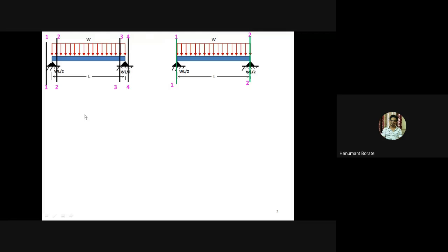Now SF at section 1-1. Now follow the sign convention rule. Sign convention: if we take a section and consider the left part of the section, then treat upward forces as positive and downward forces as negative. Okay. Now SF calculation, SF at section 1-1, or we can say SF just left of A, means at this section, section 1-1. Now the beam goes in the right part; in the left part there is no beam region, right? So we can say SF at section 1-1 equal to 0.